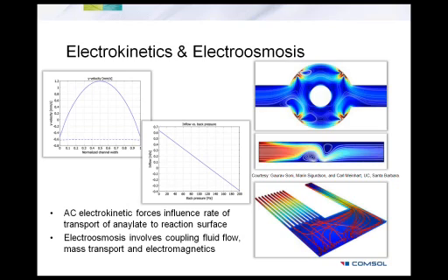So now let's talk a little bit about flow driven by electrical fields. The MEMS module can handle it, and it can simulate, say, electroosmosis for electroosmotic mixers, micropumps, and things like that, which are generally used in lab-on-chip devices. COMSOL's MEMS module also provides an interface for electrokinetic flow, which addresses transport of ionic species, which are usually present in very low concentration, say in a moderately concentrated electrolyte. This application mode basically models convection, diffusion, and also migration.